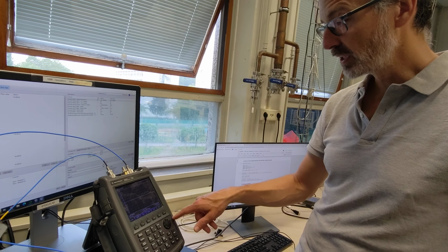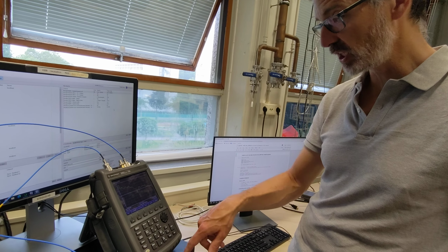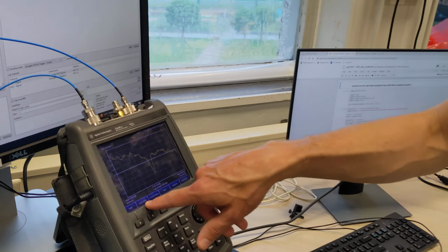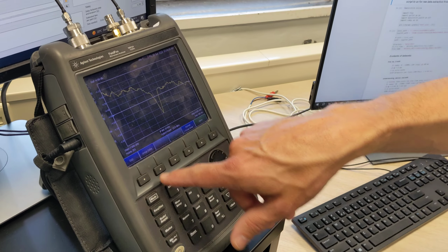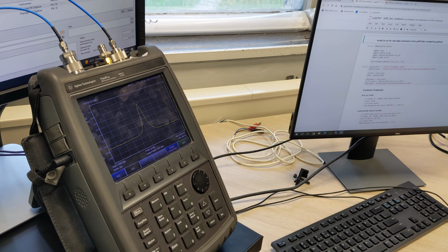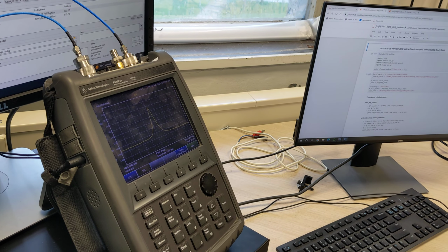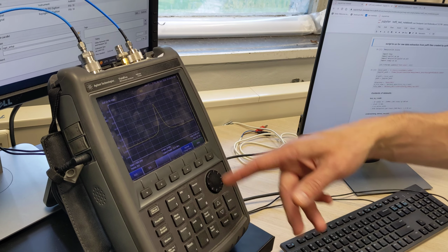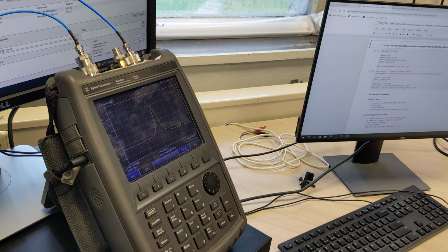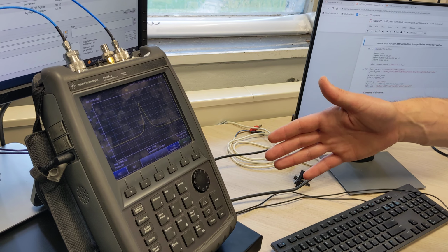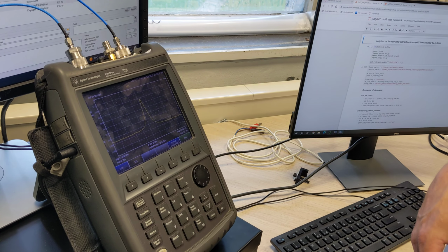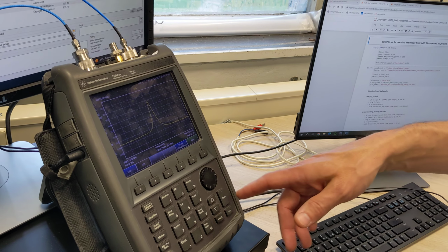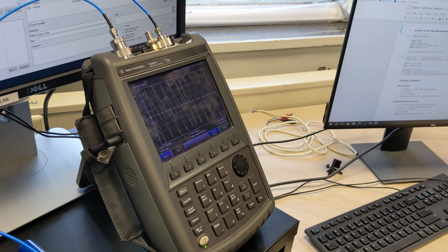That signal can be super easily seen, especially when overcoupled, by just going to the group delay button. If I push group delay, which is the derivative of the phase with respect to frequency, you get a super clear peak with a massive signal to noise ratio. That is a reflection of the fact that the signal is all in the phase when you're overcoupled with the reflection measurement.